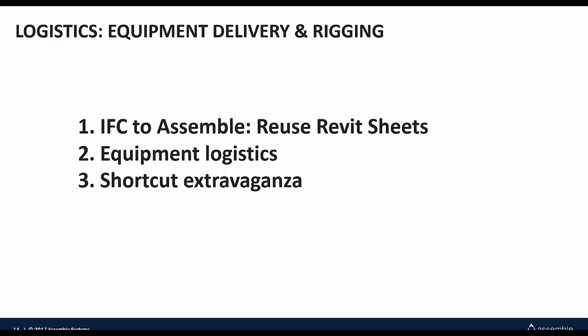That's right. And I just wanted to make sure we clarified here. It went kind of fast, and it might be a little hard to understand, but what she's doing is using the format of the Revit sheets that are there and replacing the components from the model objects in Revit with the ones coming from Tekla. And for what it's worth, Tekla, as you guys mentioned, has a fantastic IFC export. Their data and their geometry is organized really well and is consumed into Revit very nicely.